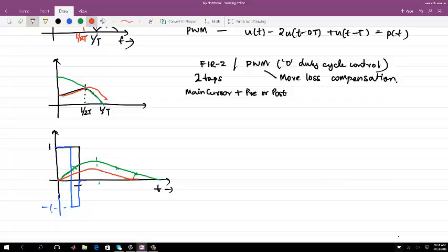Then consider the output response of the negative part of the pulse, which will be something like this. Now if you look at the peak points one bit apart, this will cancel out. So in the time domain, you can think of equalization as a superposition between the positive pulse and the negative pulse to lower the ISI. That is the time domain picture.